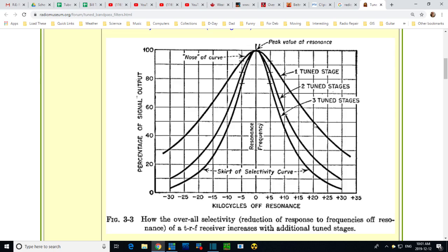Now, normally what's out here is part of the audio program. The audio program is contained pretty much in here. So you go 5 kilohertz. So if you had a 10 kilohertz tone, which I think is too much for a regular broadcast AM radio, that tone would produce a sideband out here. But typically radios, I think, are running in this area, and if they're badly aligned in that, they might even be running tighter in here.